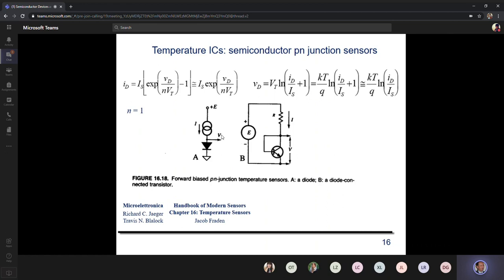If we succeeded in measuring some voltage that is given by the difference between two voltages of the form shown in the first line, such that when we make the difference between these two voltages, the term with the logarithm cancels, in that case we shall be able to obtain a voltage that is simply proportional to temperature, okay?